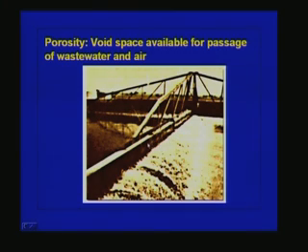So as a result, what will happen? Sometimes the wastewater will be trickling over the trickling filter. Say this arm is distributing. Similarly, we can see here also this distributing arm is distributing wastewater. After this distribution, you can see that here the medium is exposed to the air for some time. So the intermittent distribution of wastewater gives a chance for air also to circulate through the medium.